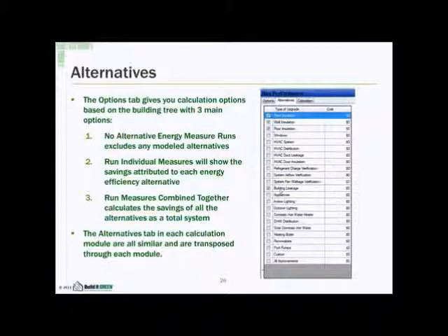Typically, we won't do building leakage because a blower door test is typically not practical in a 50-unit residence. But if you have maybe a six-unit residence and you have six blower doors, go ahead and knock yourself out with getting a building leakage reduction. But it's typically not feasible in many high-rise residential buildings.